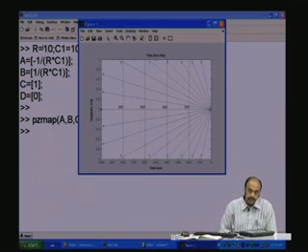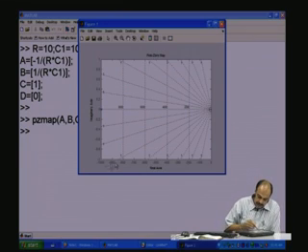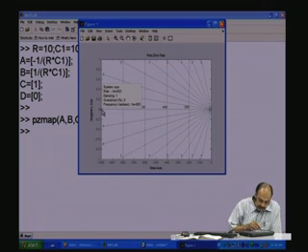So, you see the S plane, and here like I was saying, this is 0 and all going negative, which means only the left of the S plane is shown; the right of the S plane is not shown here, because there is nothing there to show, there are no poles there. So, all the poles are located, of course, here in this left half of the S plane, and that is at this point. Are you able to see this blue X mark here? That is the location of the pole for this circuit.